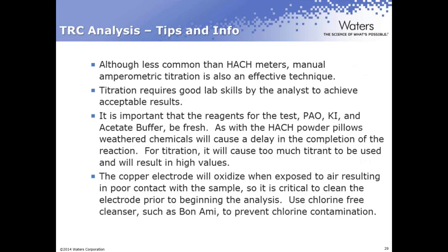For the titration method, it's extremely important that the reagents used for the test, which are phenylarsine oxide, that's your titrant, potassium iodide, and acetate buffers, those chemicals need to be fresh. Just like your powder pillows from Hach, as the chemicals get older, they weather, and they cause a delay in the completion of the reaction. For the titration, a delay in the reaction causes you to add more titrant to the sample and will cause your values to come back high. So make sure that those chemicals are all fresh.